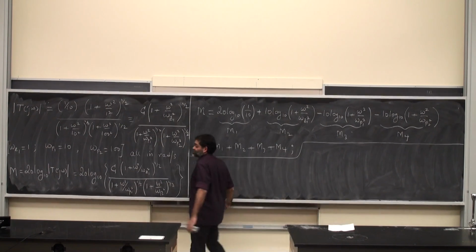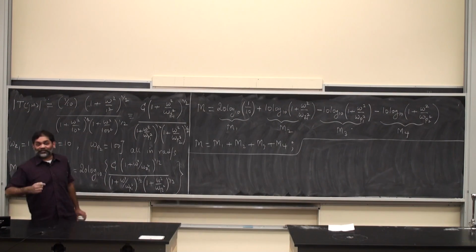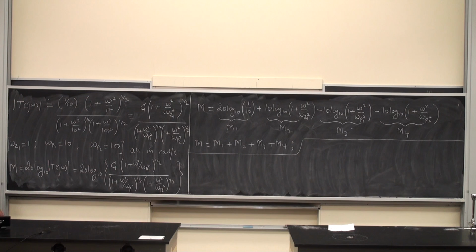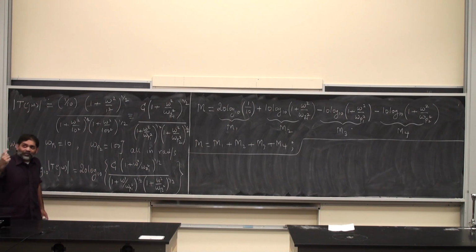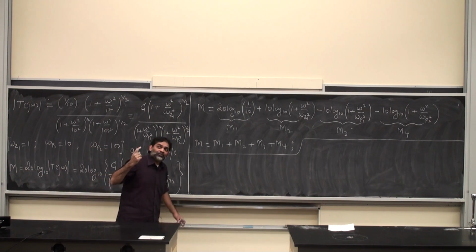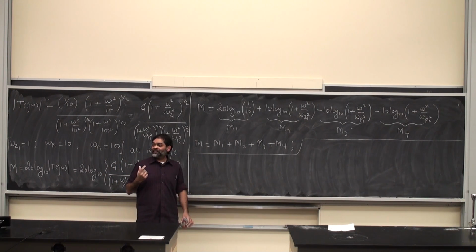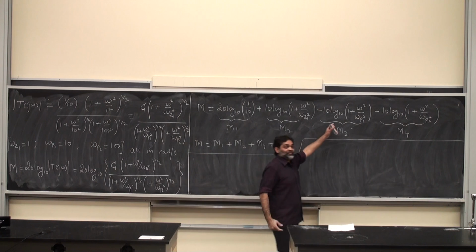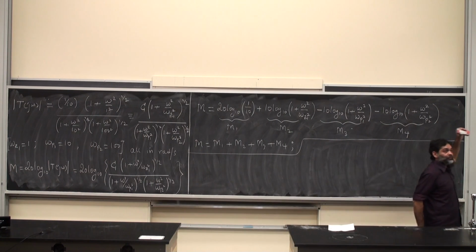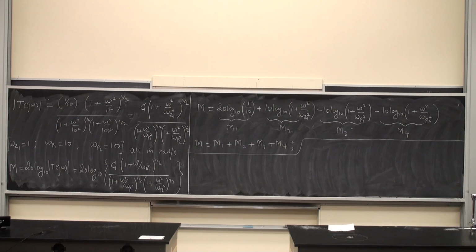And all I have to do is perform asymptotic analysis 4 times, which is fairly straightforward in this problem, because you've taken a second order system and split it into multiple first order pieces. Essentially each of them is a first order piece, which we already know the behavior of. Any questions so far?